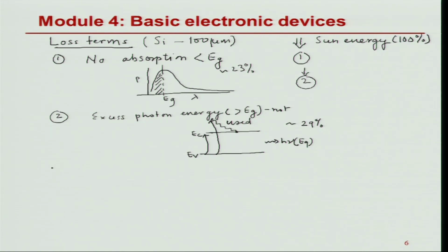So, let us look at the third part where I lose the energy, and this is where I lose the energy because of my VOC. The larger it will be, the larger will be the efficiency, and the ideal VOC can go only as high up as band gap or the built-in potential, and it never goes up to that limit. So, it is always a little bit less than the band gap. If I could make a device with the maximum Eg, then I will have the best efficiency, but there will always be a lag between VOC and Eg.